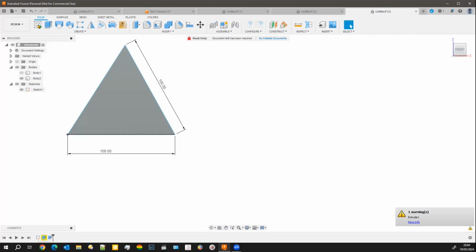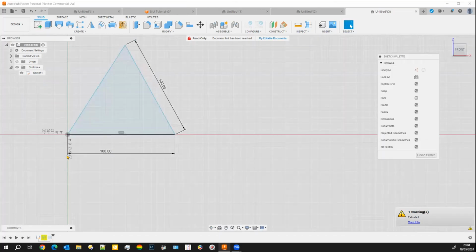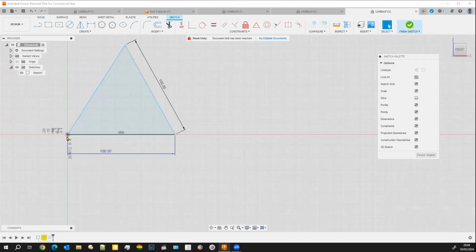And if you remember, if we go back into the sketch for this one, we can see the origin was that 100 and I drew that line, then I drew this line from there to there. So the origin of this line was down here. So when I changed the dimension on the solid, it kept the origin and extended the line away from the origin or would bring the line closer to the origin. Does that help, Paul? That explains it well, Russ. Thanks very much. Okay, stop share.